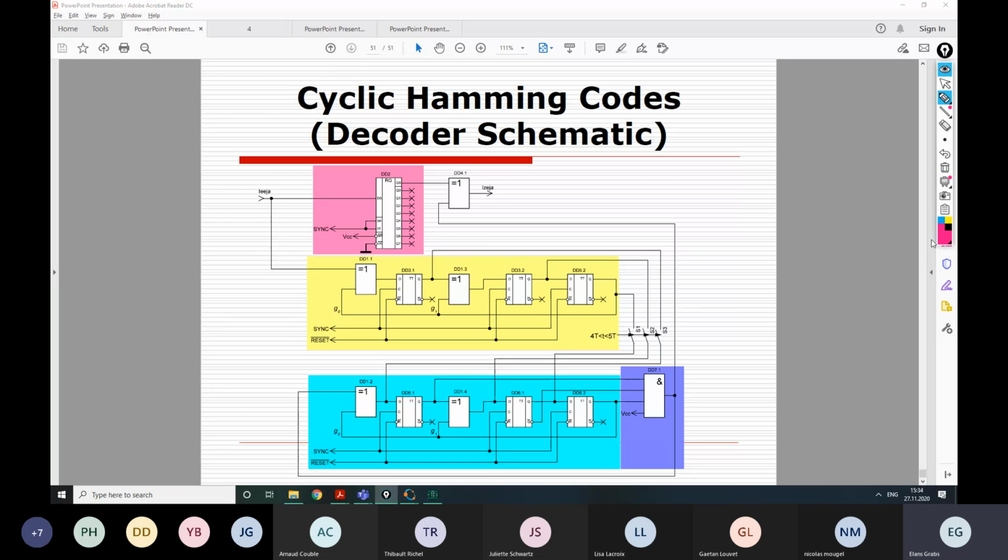Then we have the error detector here, which is an AND schematic, right? And as I have told, for the syndrome of 1, 0, 1, which is sent to this error correction schematic, we must output direct outputs where we have 1, that would be here and here, and inverse output where we have zeros, that would be here. And then this is put here when we correct.